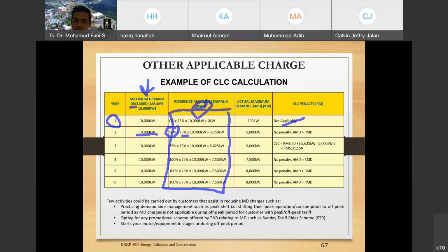But no charge for CLC. CLC charge, connected load charge, no charge. But you need to look back at the connection and your load and your appropriate size for the transformer, and advise your boss to upgrade the substation. If you are at 415 V, try to upgrade to 11 kV medium voltage, or from 11 to 33, and if not, then go to the high voltage one.